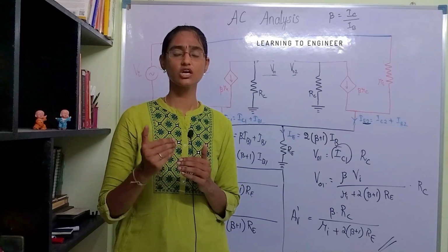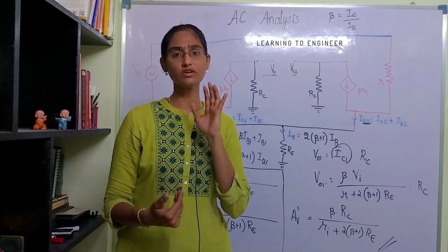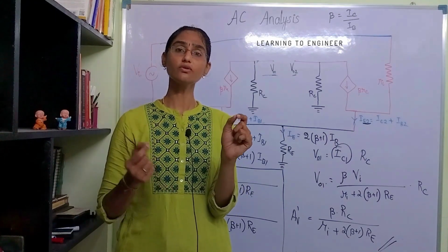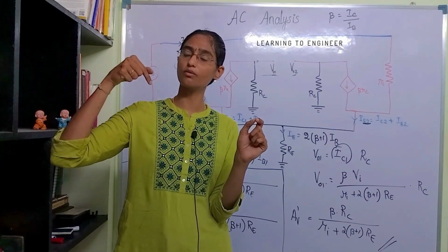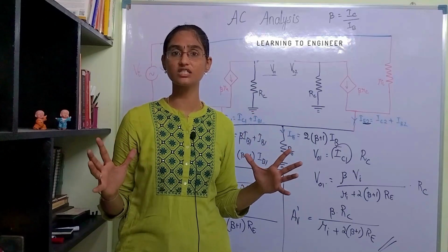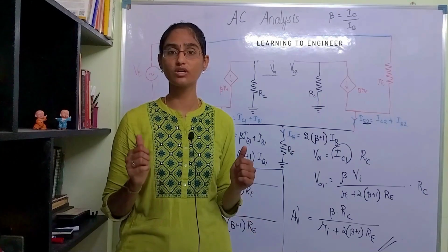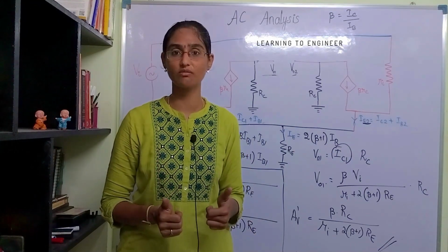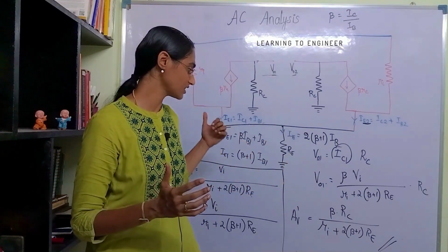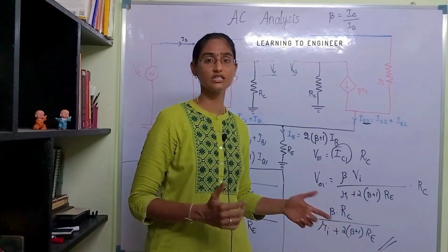So what voltage should you apply to this OPAMP to make this 0? Let us say for example you are getting a common mode voltage of 0.5 volt. If you supply this 0.5 volt to the common mode pin of your IC, this will nullify the effect, and it is almost as if the common mode output is completely zero. So you have totally suppressed the common signal and you have amplified the differential signal. Okay, so we have seen the derivations for the differential gain and common mode gain in this video.